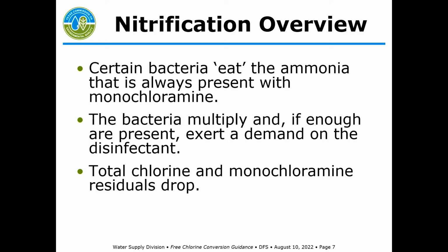So what is nitrification? There are certain bacteria that every distribution system has. Our distribution systems are not sterile. There are microorganisms out there, and certain ones of them use ammonia as a fuel. So they eat the ammonia, and they make more bacteria, and if you get enough of them, they exert a demand on your total chlorine or monochloramine residuals.